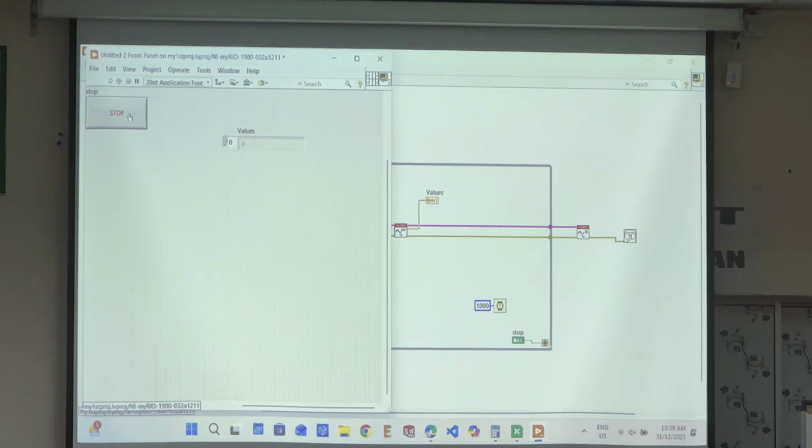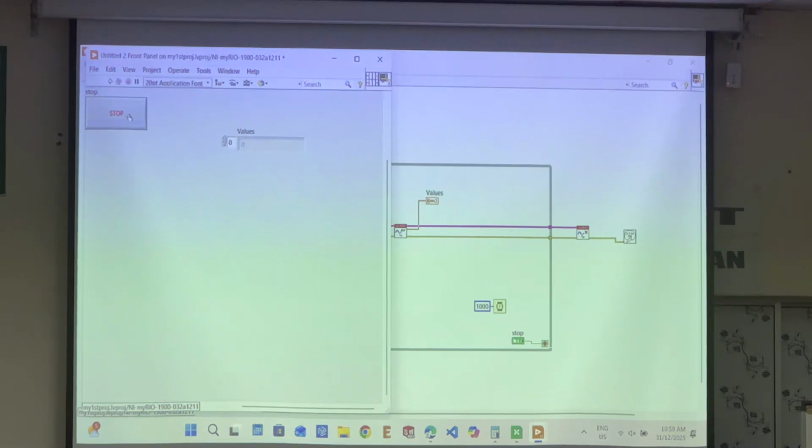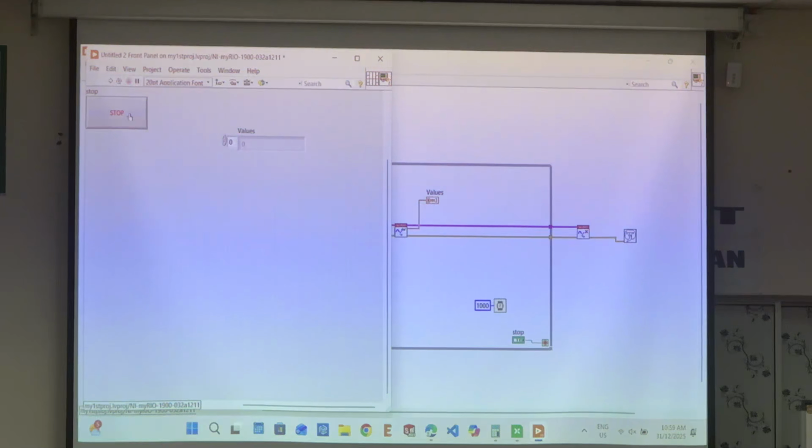250, right? 250. You are very clever. Before this I asked, everyone already knew. So you know you get information from the previous group. Okay, that's good. We expect 250 millivolt, right? Correct. Everyone agrees, the back agrees. If it is 25 degrees in this room, so we expect 25 degrees to be 250 millivolt.